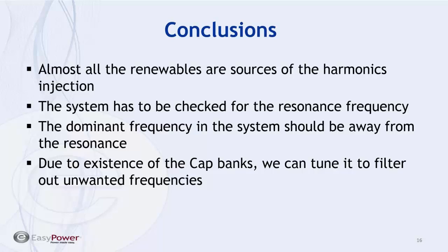Keep in mind that whenever you add a reactor to a cap bank to tune it, in fact, you are impacting the reactive power capability of the cap bank. So that's one extra calculation you have to make sure you do.